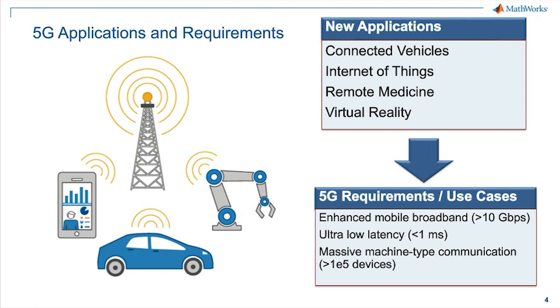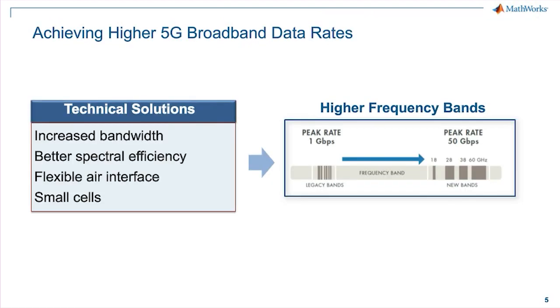So one standard is trying to achieve all of that. Let's see what technology is enabling all this. In terms of technical enablers, if you want to go from 4G to 5G, you need to look at the requirements. You want increased capacity or increased throughput in your network, right? One way to increase the capacity and throughput is to increase the bandwidth and increase the spectral efficiency, which is how many bits per second per hertz of bandwidth.